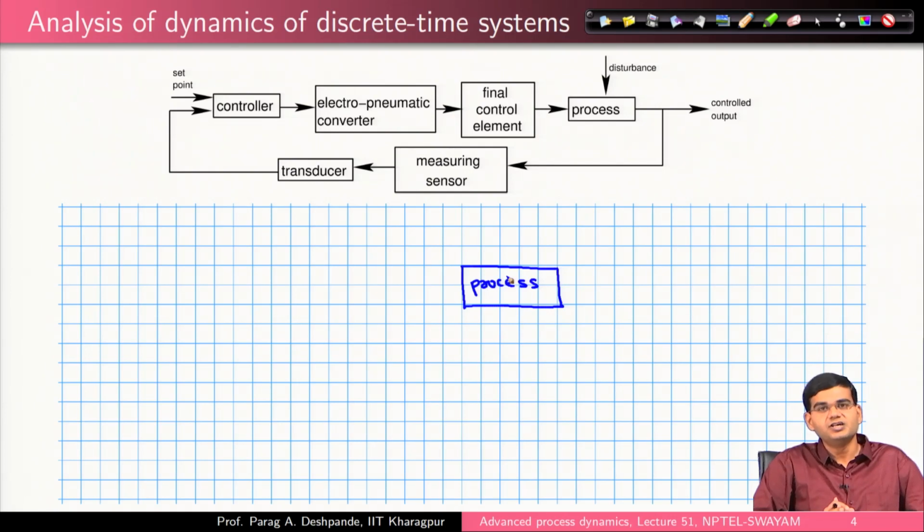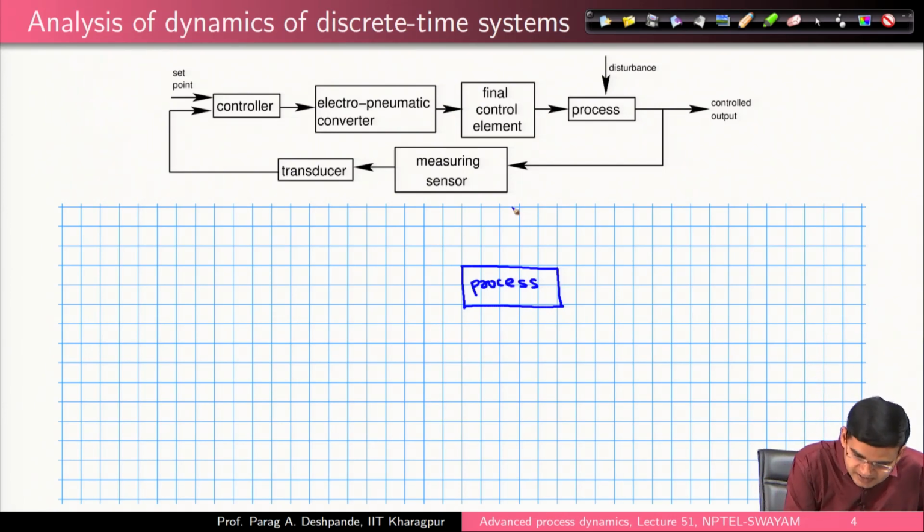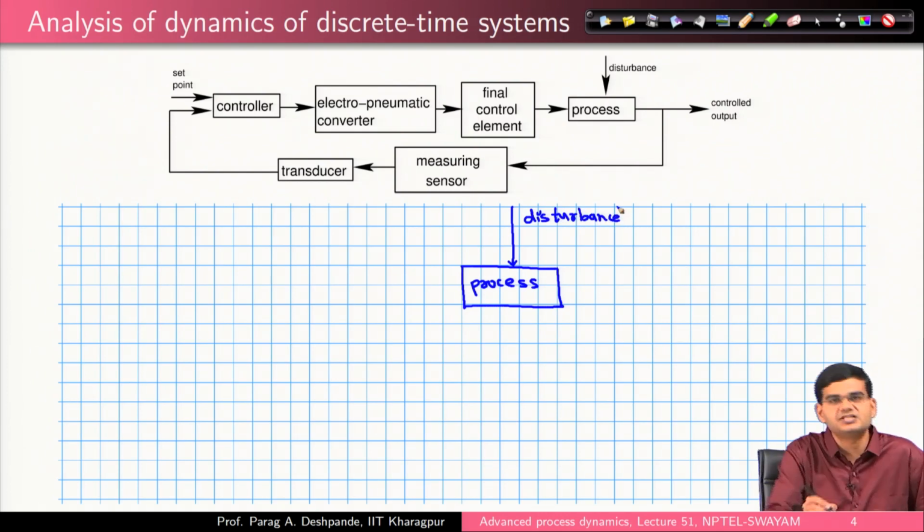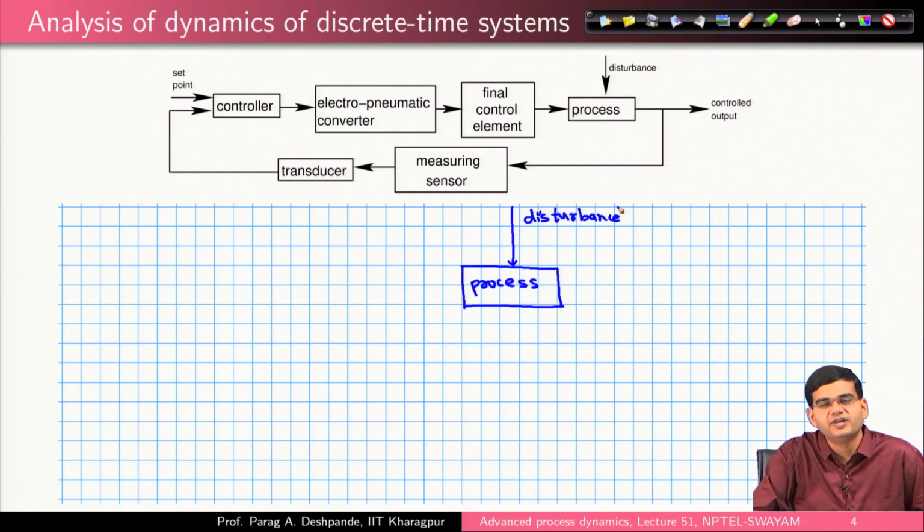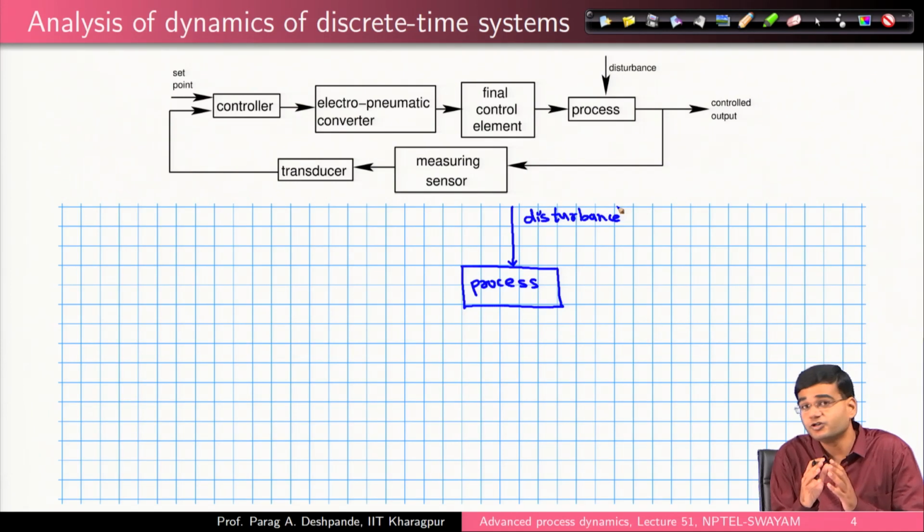So, the input to the system would act as the disturbance. And there can be several reasons for having the disturbance. Some pump may fail, some heating element may fail, the flow rates may change. There are various reasons for which the disturbance may occur in the system, and because disturbance has occurred in the system, the steady state of the system would change, the system would tend to move to a new steady state, right. But that is not what you want, right. You want the original steady state to be maintained.